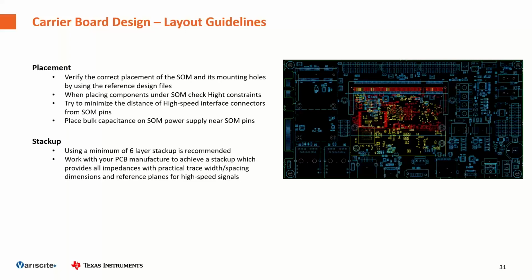About the stack up, we suggest using at least 6 layers, and we suggest working with a PCB manufacturer that can achieve this stack up while being compliant with all other constraints that may be required, specifically for the high-speed signals. For example, I'm referring to the SD cards that can reach up to 200 megahertz. If there is any misalignment in the design, you may experience problems with some specific SD cards that may be, let's say, more sensitive. Okay.